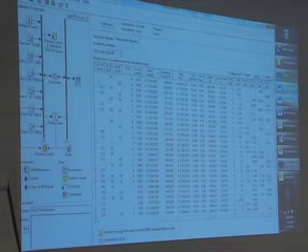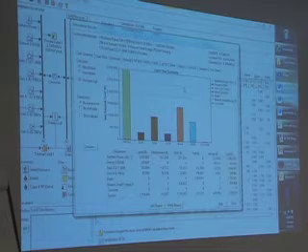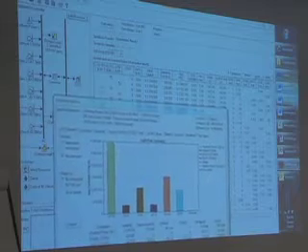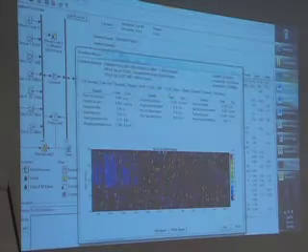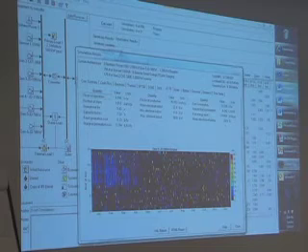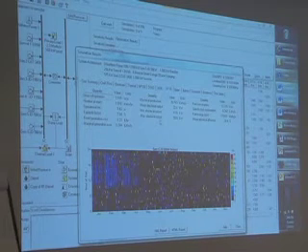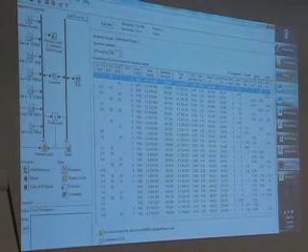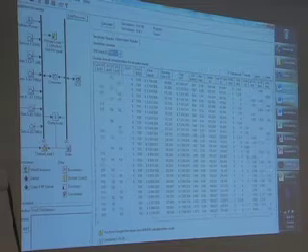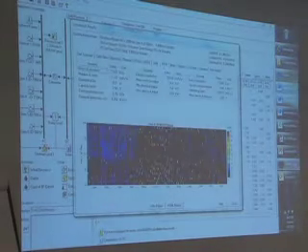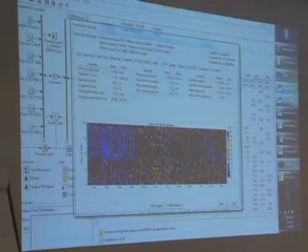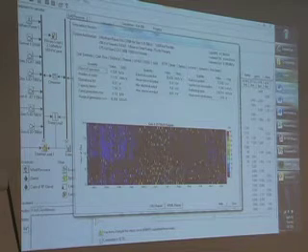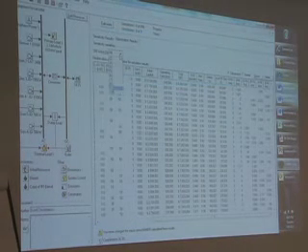So if you wanted to look at that more closely, what you'd find, which generator is that? The JD58. So the average electric load here is 22.4 kilowatts. As we reduce the operating reserve, it's going to run for more hours, but actually at a lower load level, 21 kilowatts. The efficiency is actually going down. So you go, well, that's bad.